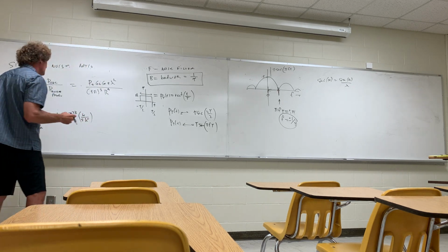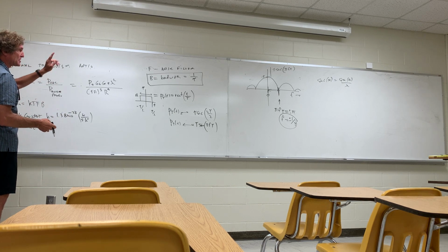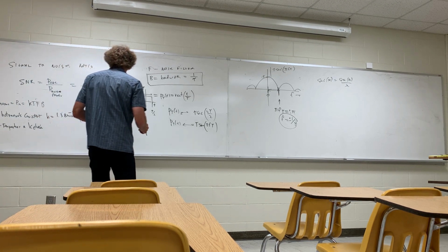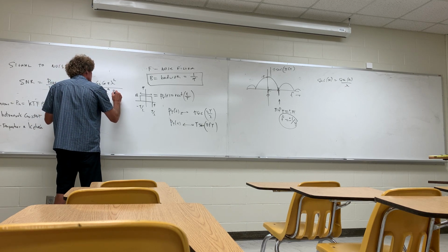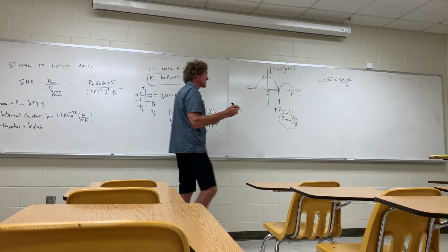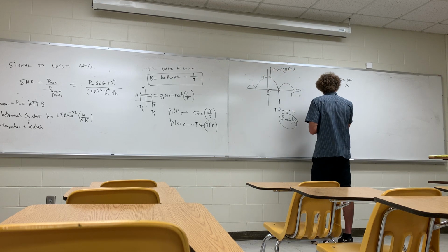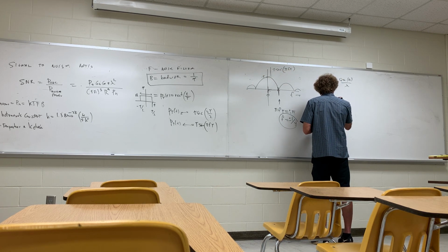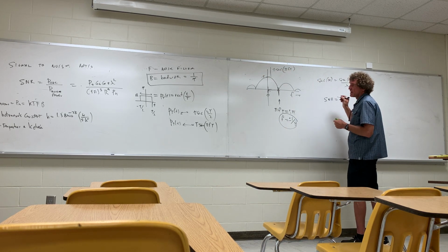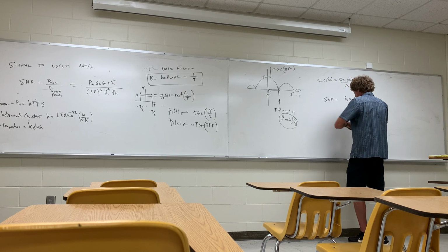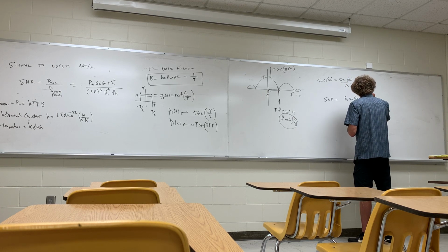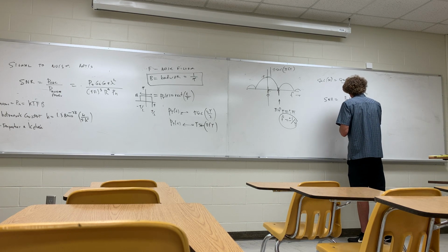Now when I'm going to get signal and noise, I'll put it over here. I'm going to take this and divide it by noise power, P noise. Now I get this, and I'll put the final thing. The SNR, signal to noise ratio for a waveform, will be equal to transmitted power, gain of transmitter, gain of receiver, sigma, lambda squared over 4 pi cubed r to the 4th.